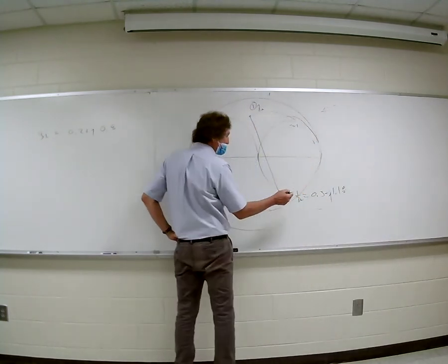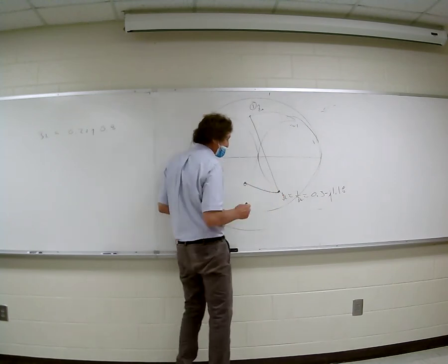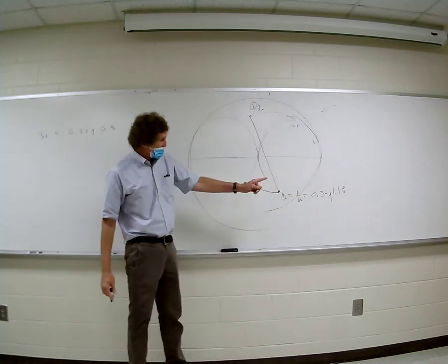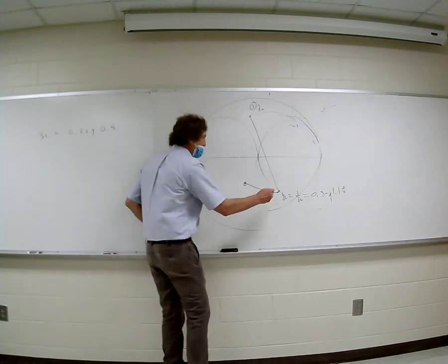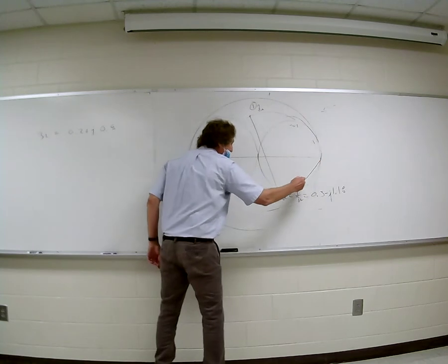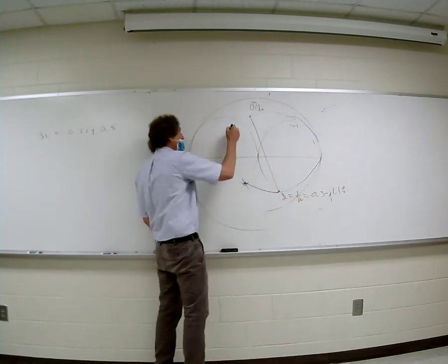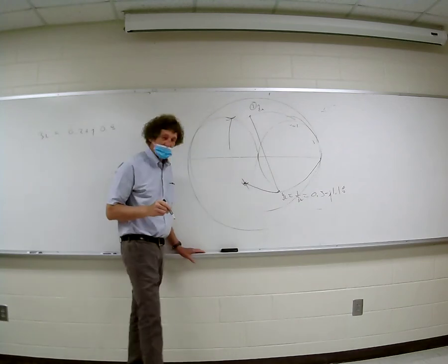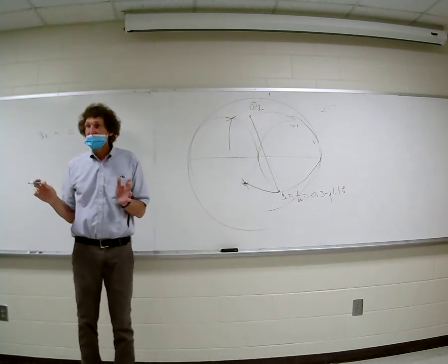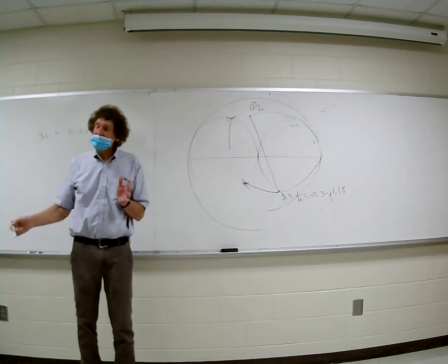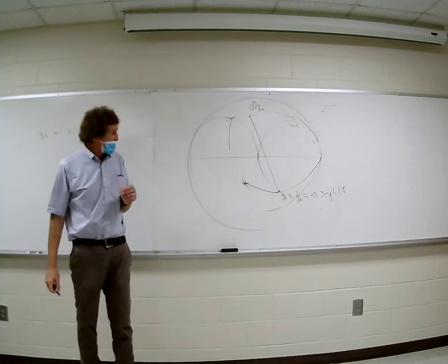Well, I'm going to go from here and I'm going to add something to get to this rim. Now this is minus j1.18. If you go on the trajectory, you got to go on that r equals 0.3 circle, the large arc. Find out where it intersects here, and there'll be a conjugate point here that intersects. Y'all understand that? I call them trajectories. It's the arc of the 0.3 circle. But it's going to hit it.